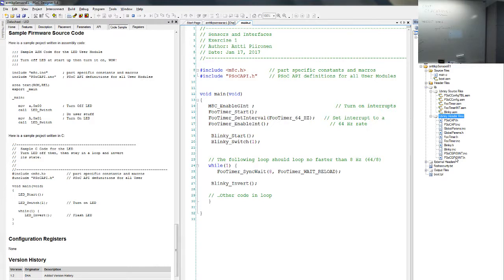This one actually is connected to +5 volts. So that is our switch 1. In order for that to work, you need a pull down resistor that keeps it at 0 until you press the button, when it gives the high input.